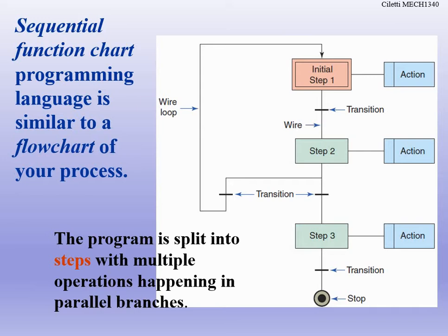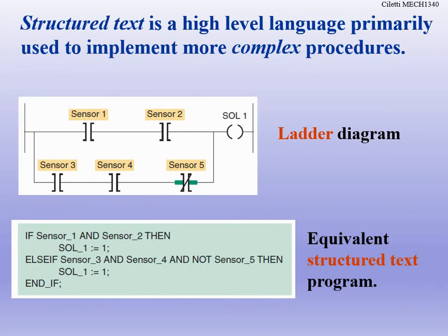That then interaction. So, an example would be like on station 1 of the 870 trainer, where we have the feed cylinder extends. Well, that might be our initial step, right? What action has to happen? Well, when it extends, then what has to happen? Oh, we have to lower the pickup cylinder, and we have to turn on the vacuum. So that might be our action that we're doing, all right? And then once that happens, we have to retract the feed cylinder, even though that one's automatic. But I'm just kind of throwing it out there. You need to understand things sequentially, step by step.